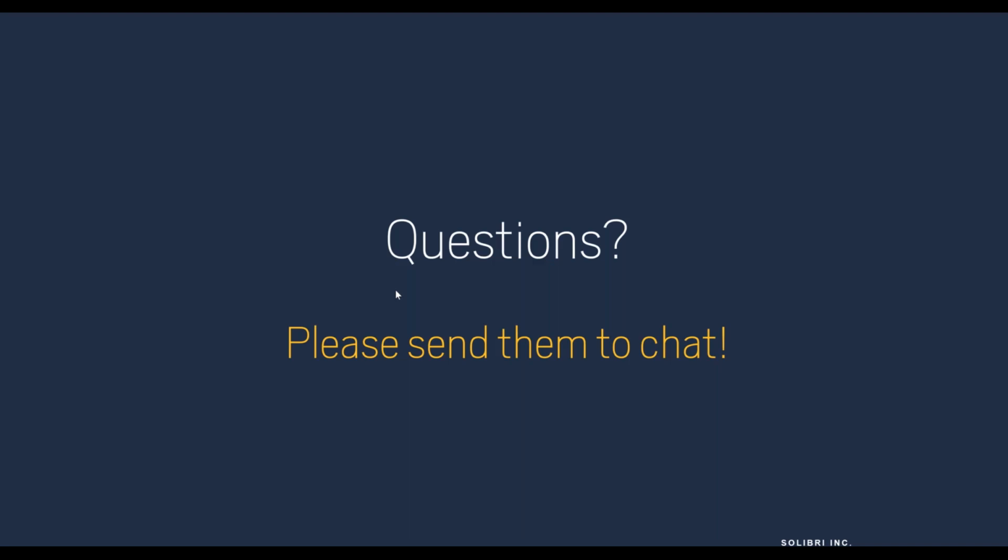Okay. Solibri can check this information with some rule sets, like a classification. As Dielen told us, we have the quantities in the quantity tab in Solibri, but I need to guarantee that a window will be a window in the IFC classification, because if it's not working, Solibri cannot reach this number and provide this number for us, okay?